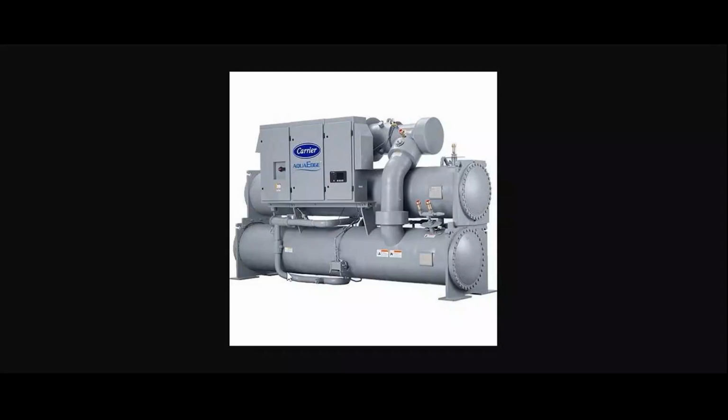So this is how the chiller looks. Are you able to see the chiller here? Okay, this is how the chiller is. One is the condenser, one is the evaporator, and we have a compressor, and somewhere you will get the expansion device. This is called a water cooled chiller, sir. Water cooled chiller means if the condenser coil is cooled by water, then it is called a water cooled chiller.